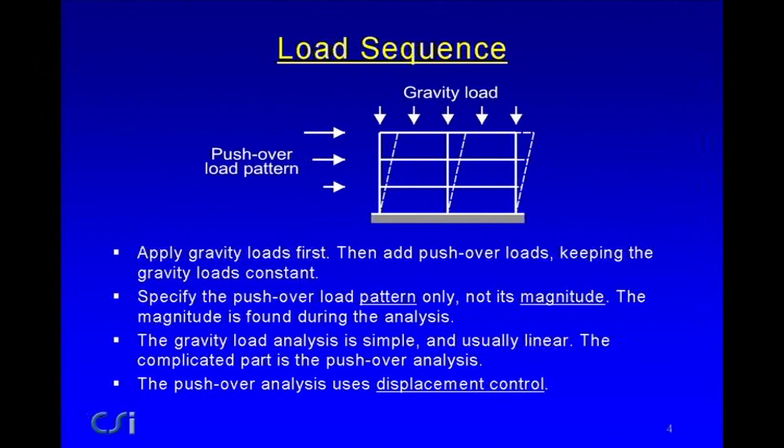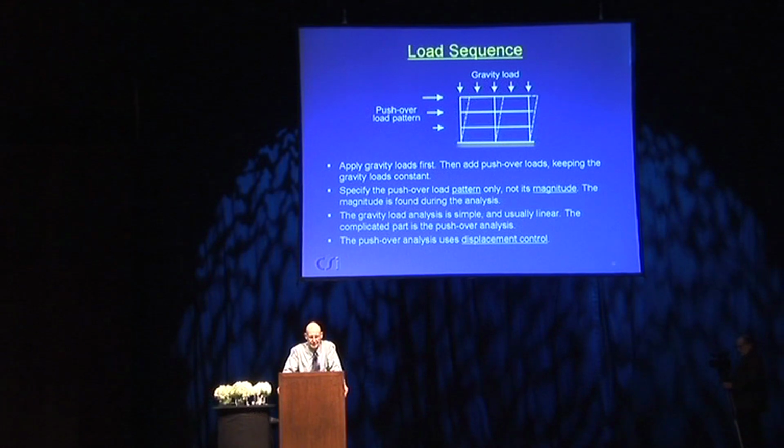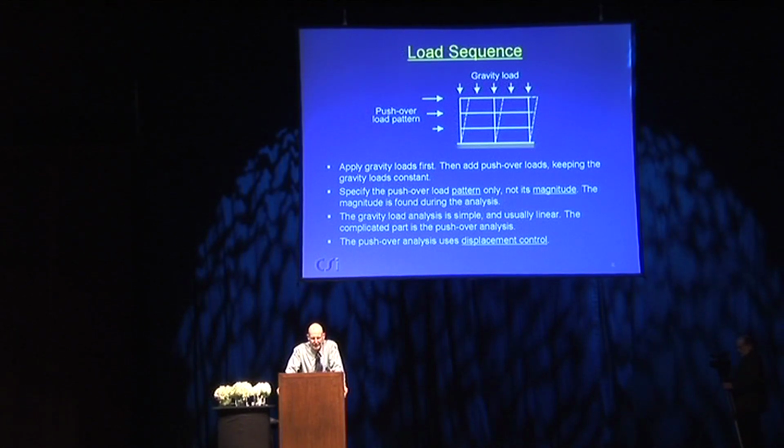We're talking here about a static pushover. So the load sequence is to apply gravity loads first, and then keeping the gravity loads constant, add the pushover loads. You specify the pushover load pattern only, not the magnitude. You find the magnitude during the analysis.